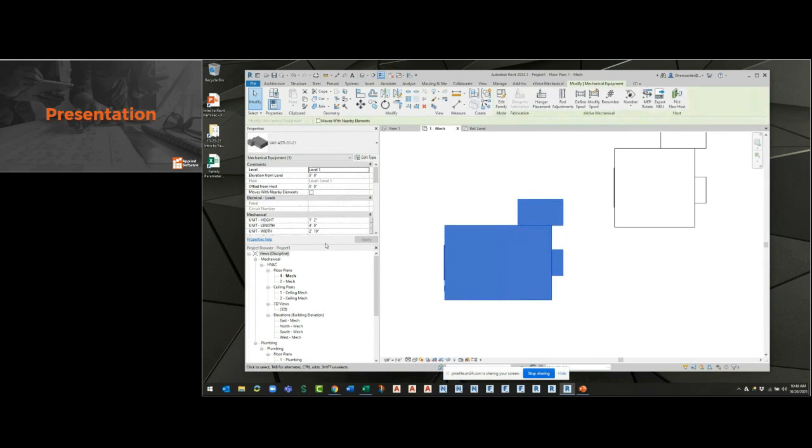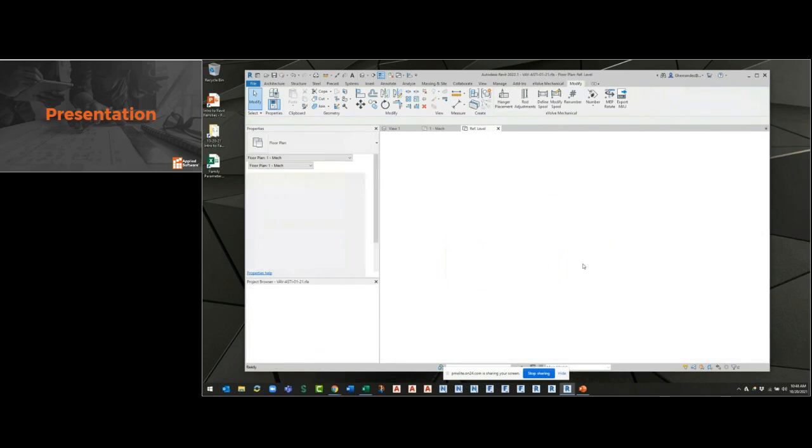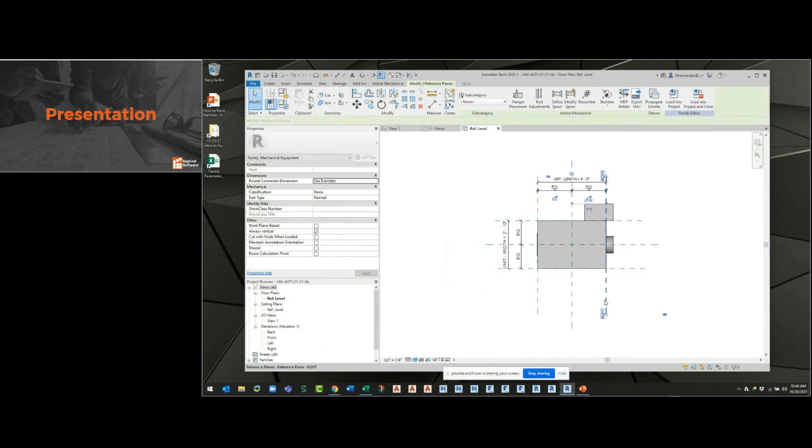I still want this kind of control over the dimensions where they're instance like this, but I don't want to have my users stretch this stuff out by accident, right? That's a big no-no. So it also has to do, again, with the reference planes that you built, the bones, right? So you have the reference option here, is a reference or not, okay?